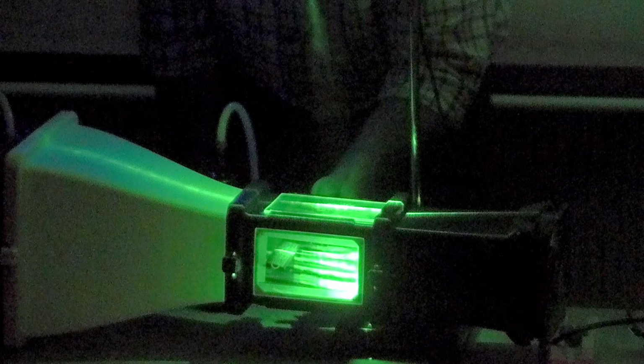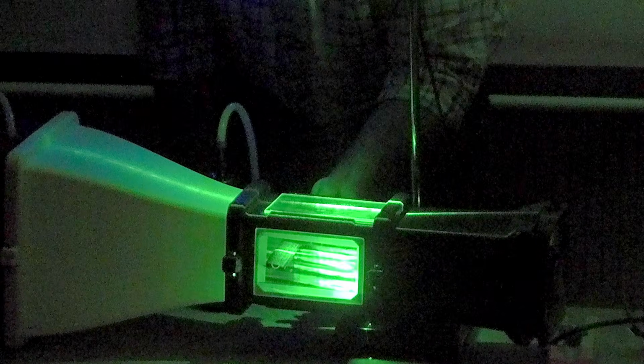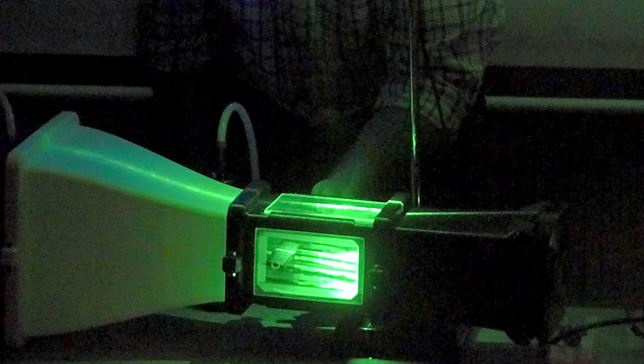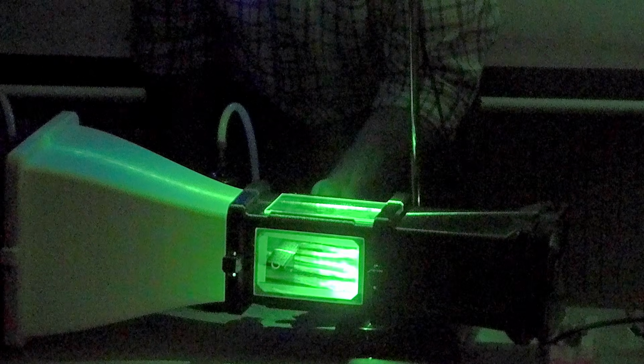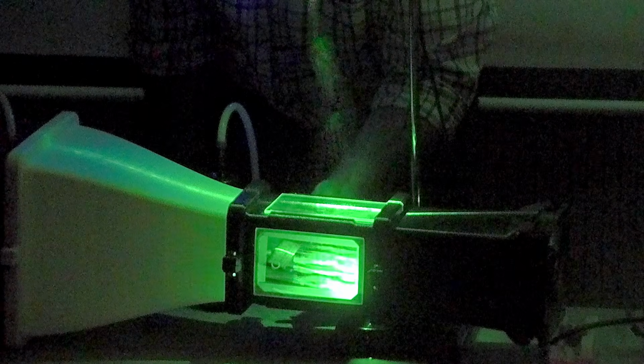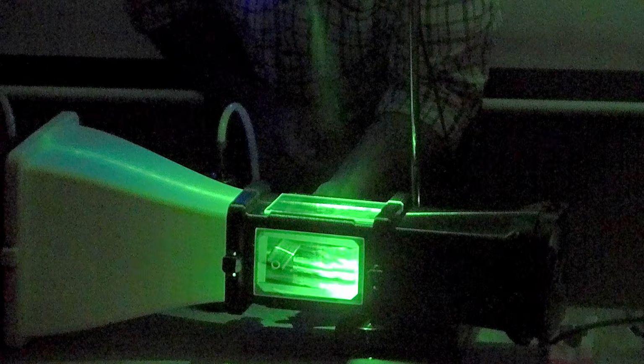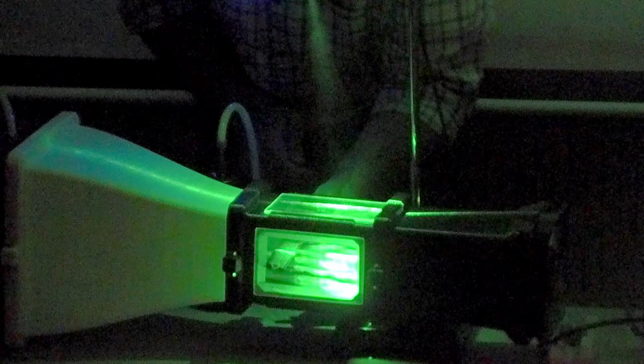So now do you see? Do you see the streak lines that are passing by this airfoil? And there is absolutely no flow separation as your flow passes the airfoil. But see what happens when I change the angle of attack to something positive, and you see what starts to happen. The flow is immediately separating from the top surface, the boundary layer is separating, and when I put it back to zero or very small angle of attack, you will see that there is no flow